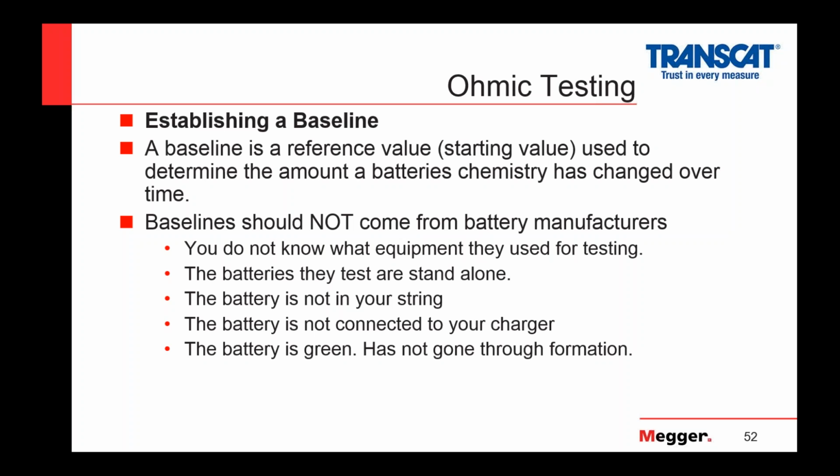The battery's not in your string. The battery most likely is a green battery and hasn't gone through formation. And you also don't want to get the value from a test instrument manufacturer because you don't know the condition of the batteries they used for the testing.